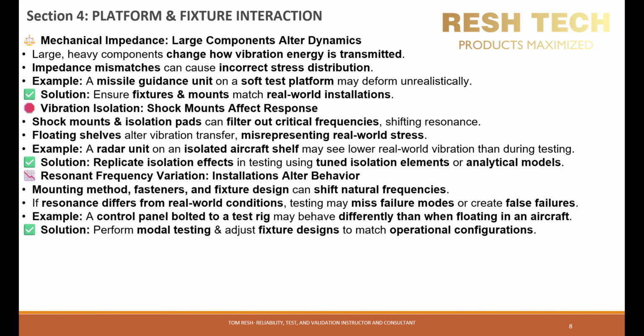The solution to this is, if the vibration isolation is present in actual use, replicate its effects in testing using properly tuned isolation elements or modeling its behavior analytically. Resonant frequency variation: installations alter natural frequencies. The natural frequency of a system determines how it responds to excitation at specific frequencies.